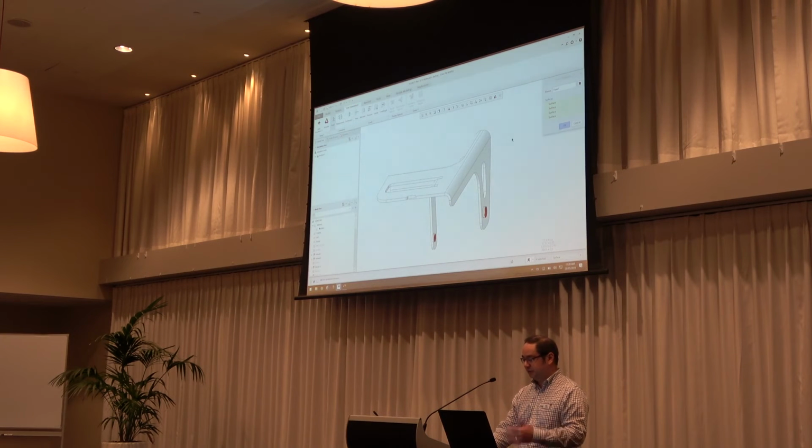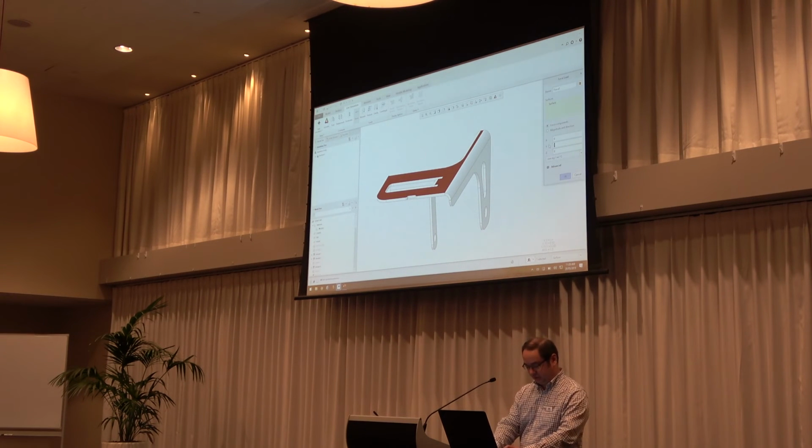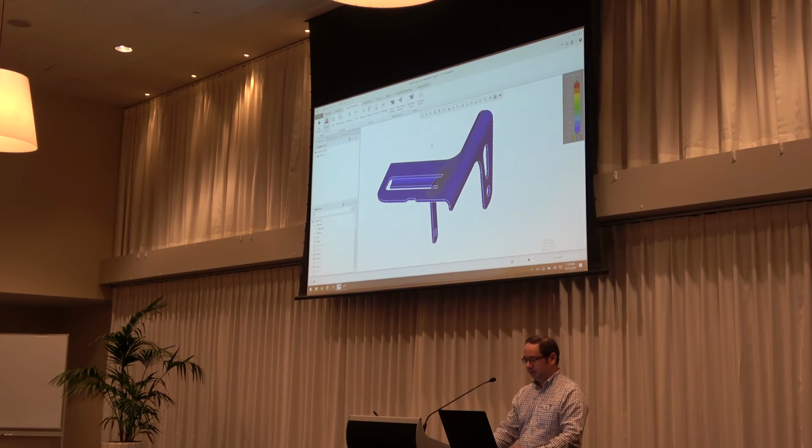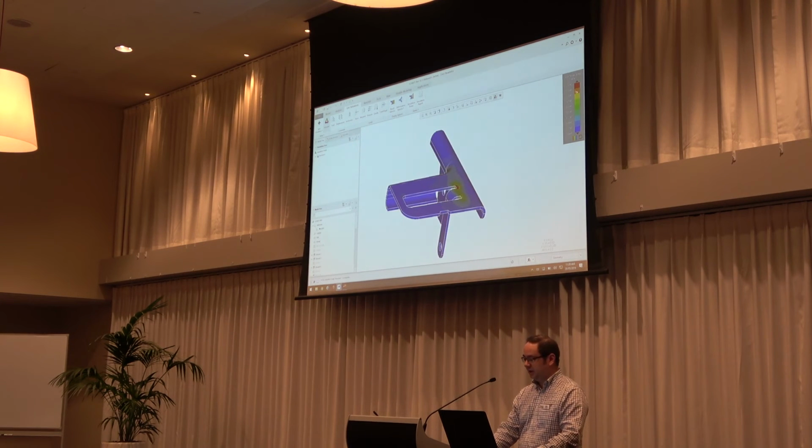So those of you who might be using Creo Simulate, you can see it looks very much the same. I'll put a force on here on my surface, give it a magnitude and newtons, like so. And we are now ready to run simulation live. So I could start the simulation here. It's actually just like a rendering option in the graphics toolbar as well. Let's turn the simulation on. Okay. And there it is, done. Okay, so I've run that simulation. So I've got some results there. I can see my stress.